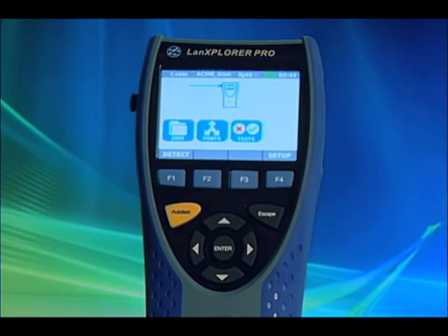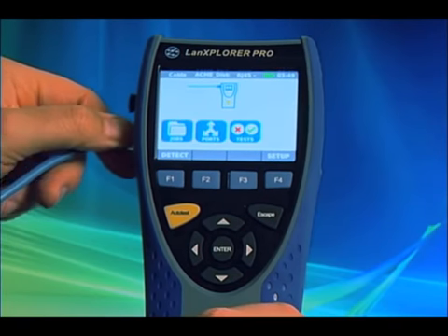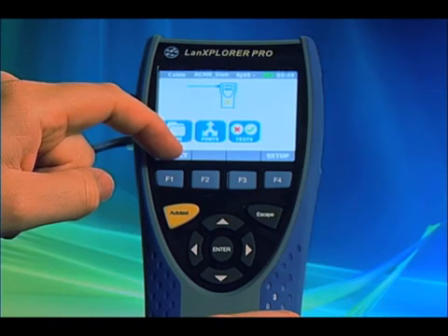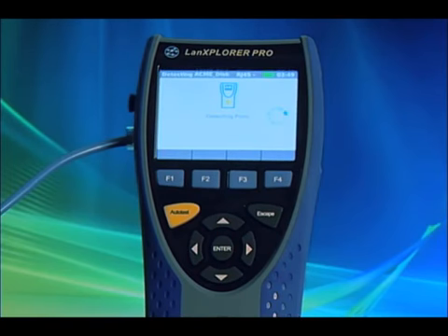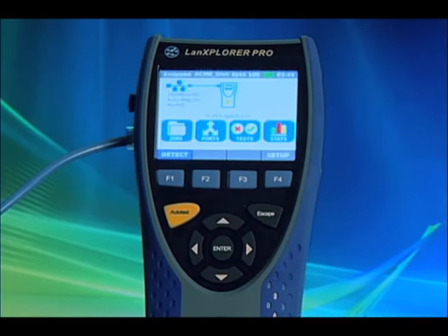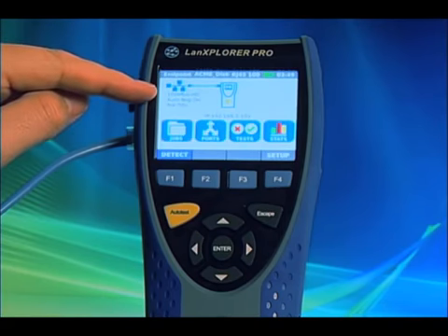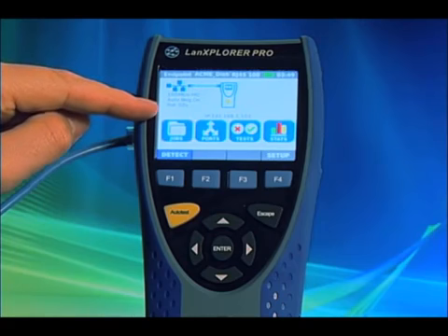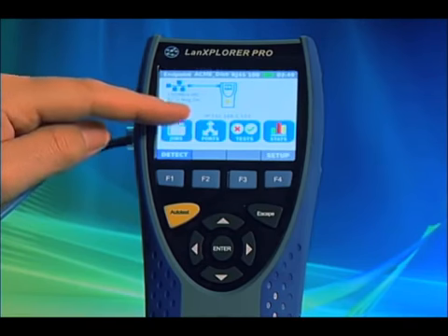This is the PoE test. The first test we'll show is the load test. Take the PoE line, plug it into the left side, and press Detect. In this case, we see the link speed, negotiation, and PoE shows 50 volts at this IP address.